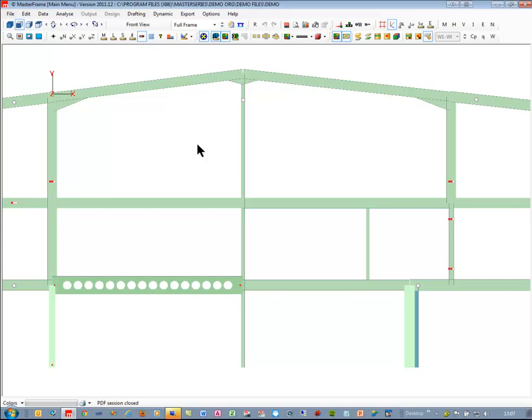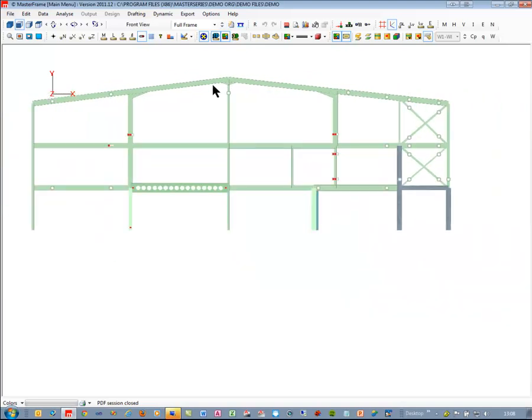And interestingly, just because this is a hangover frame from a steel frame analysis type tutorial, this column here, while it exists, doesn't provide any vertical or lateral support to this. So it's actually not doing anything. This apex will sink like a normal portal frame. So that's my basic sections.